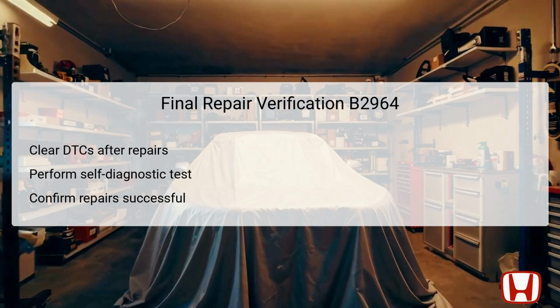After conducting the necessary repairs and replacements throughout the troubleshooting process for DTC B2964, it's essential to verify the integrity of your work. Start by clearing any existing diagnostic trouble codes using the Honda Diagnostic System, HDS. This action resets the vehicle's DTC memory, allowing you to check if the repairs effectively resolved the issues.